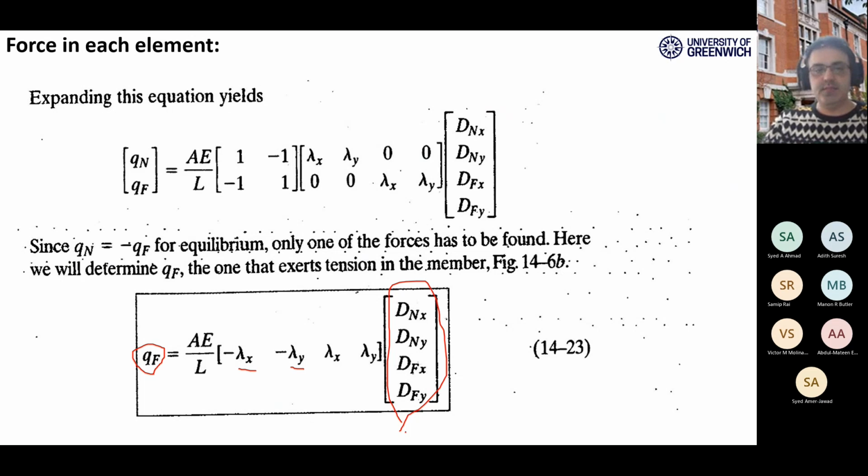So if you implement this formula for every single element, you can simply get the internal forces for each element. You only need the 5 parameters you used for assembling the stiffness matrix, the 4x4 individual stiffness matrix, and the obtained final deformations in the beginning and end of each element.